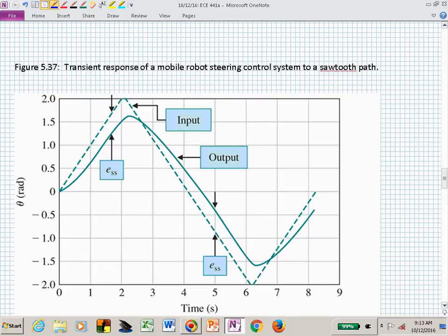And in this particular picture, I hope you can see that, oh, about this time, we've reached a consistent difference between what we've commanded and where we actually are. And that's now the steady state error. Then you turn, and obviously there's transient. After you've made an adjustment in your input, and you now have to say, oh, if I'm looking for the steady state error in this second interval, I need to wait a while. Maybe I'll just call it at 5. Or maybe you'll call it at 5.5. They should be the same.